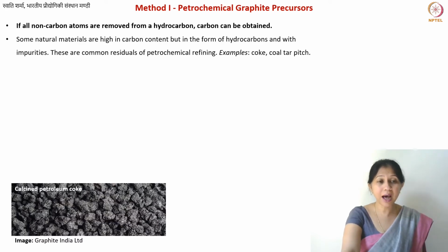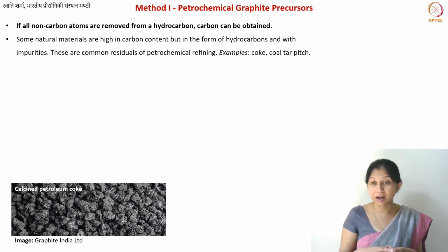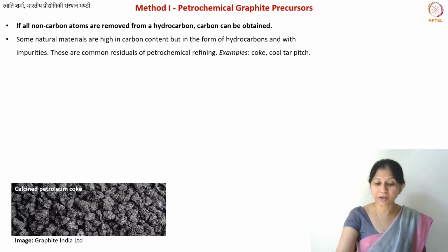Okay, now here is a picture of coke. So this is how coke or processed coke looks like. We do a certain process known as calcination. Calcination is also a heat treatment, but you may have some air in the case of calcination. Air means you can have some oxygen, so there may be certain burning that is taking place. You're basically trying to burn out the organic impurities. After the calcination, you get this kind of raw material which is known as petroleum coke.